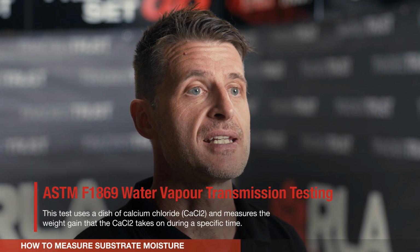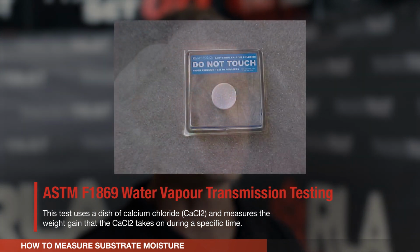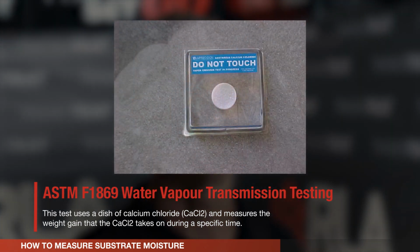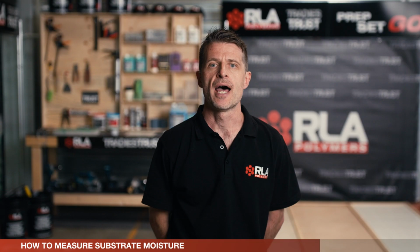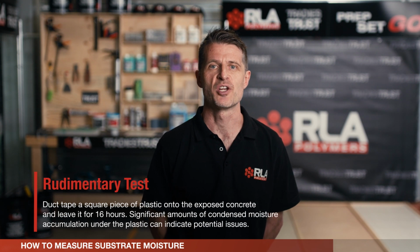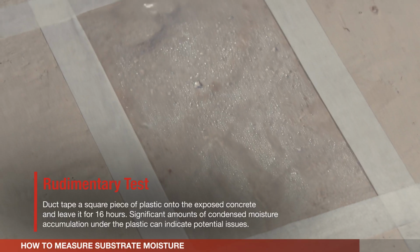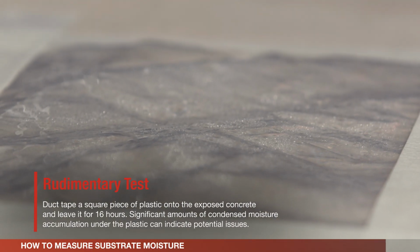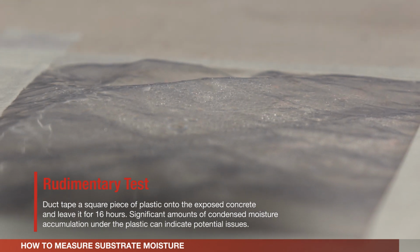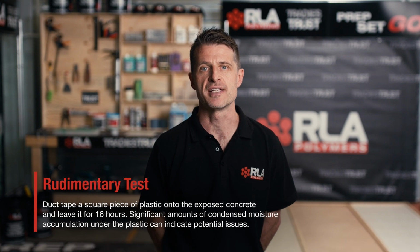ASTM F1869 is a water vapor transmission test, and this test measures the rate of water vapor evaporation by using a desiccant, which absorbs moisture from the substrate and is then weighed over a certain period. And then there's the basic rudimentary test. So before the advent of fancy electronic testing, contractors would often duct tape a square piece of plastic onto the exposed concrete and leave it for a set period of time. And the amount of condensed moisture accumulated under the plastic will give a very basic reading of the estimated moisture content.